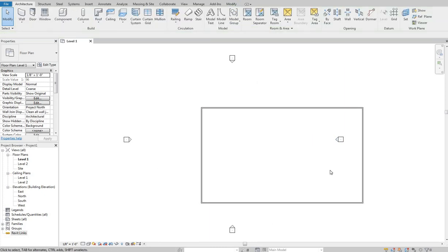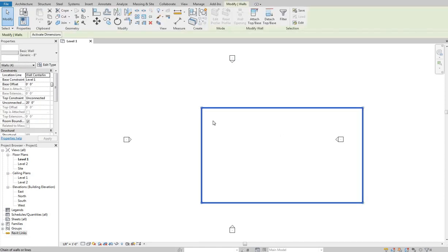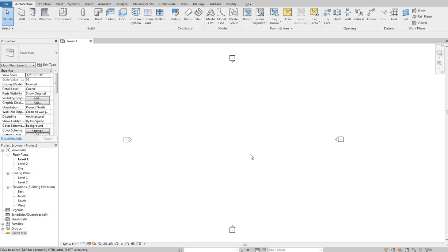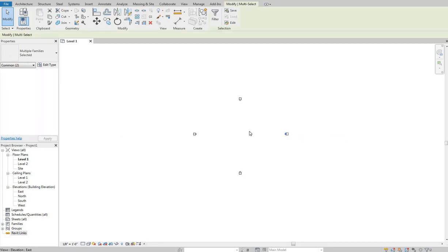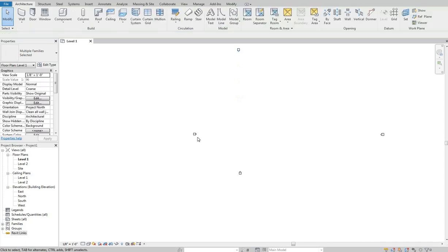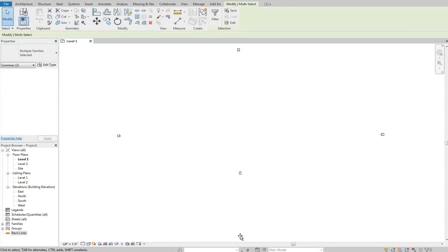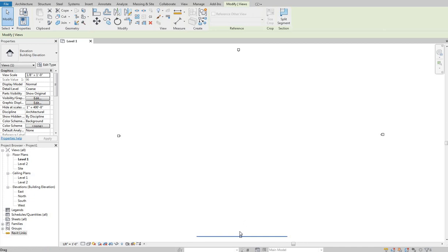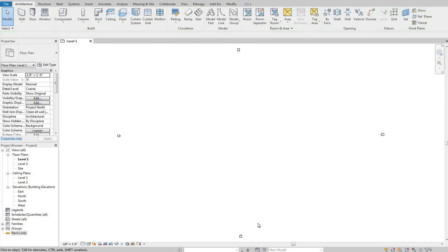So you just want to make sure that you're working within these 4 carets here. So if for whatever reason your model is bigger than this, you can always grab these and just drag them out to give yourself plenty of space. The default says that there's no limit on the elevation, so this will go on looking in this direction forever. So if this is dragged way out of view and your model is only this big in the middle, it's not going to make a difference. As long as you're within the confines of these 4 little carets here, you should be just fine.